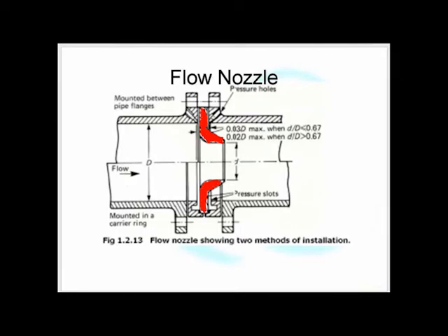Because you end up with something that still wears out, just like an orifice plate wears out, still interrupts the flow, not as much as an orifice plate, but the worst thing about the flow nozzle is the way they tend to be installed. See, this is showing a flow nozzle using a thing called a fillet. This is a fillet.